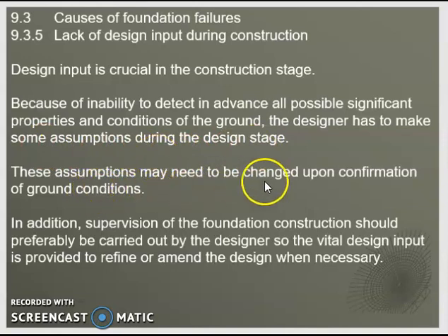These assumptions may need to be changed upon the confirmation of the ground condition, as there's more time to do the further stage 2 site investigation, or when the construction is ongoing and they discover that the ground condition is not the same. In addition, supervision of the foundation construction should preferably be carried out by the designer, so that vital design input is provided to refine or amend the design where necessary.